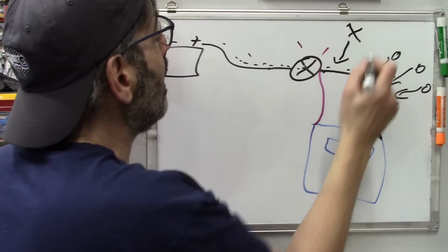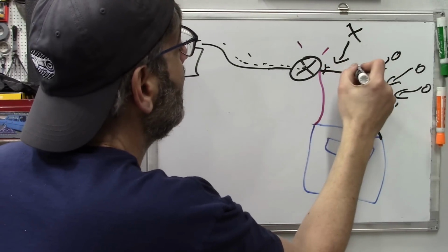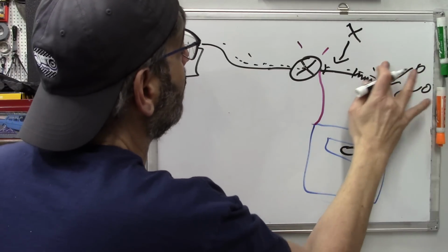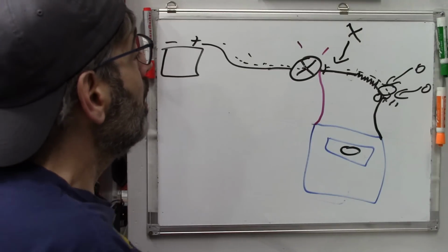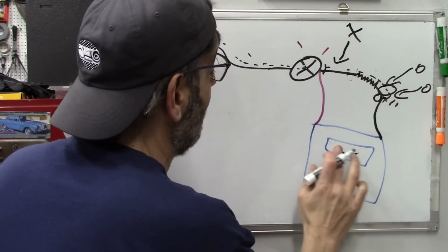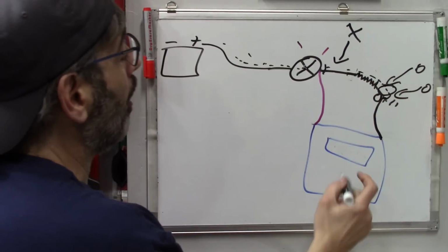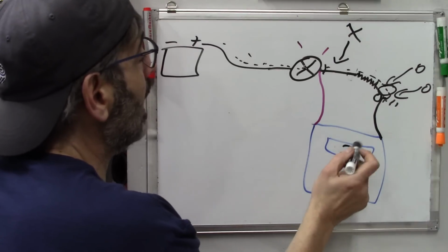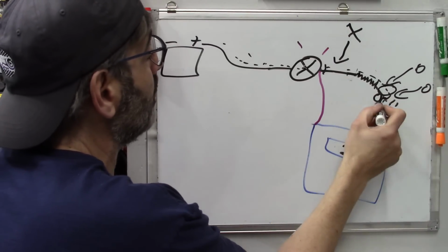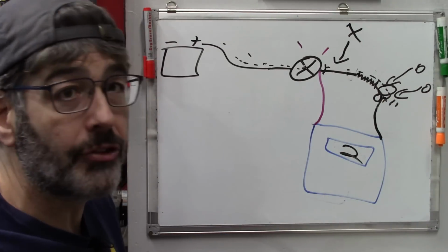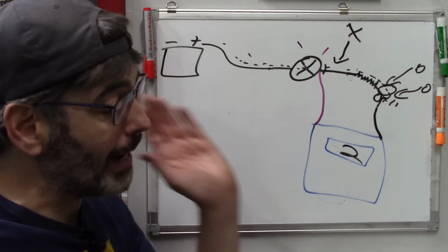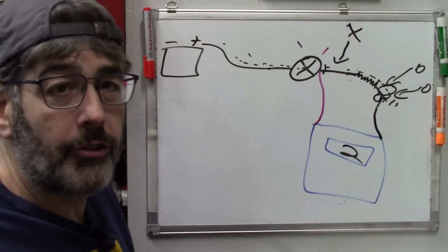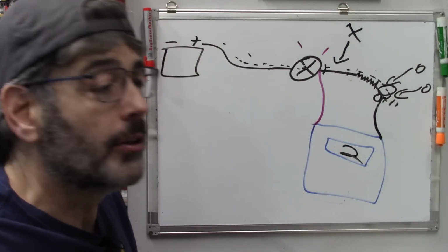We're going to have some voltage here in this area, but again, we will have 0 volts after the resistor. So if we measure anything on the meter now, let's say we measure 2 or something like that, that's telling us we have a resistance between these 2 leads. We should not have that on a ground. A ground should be clean. So that's what they're asking us to do. So let's go over to a car and see if we can do it for real.